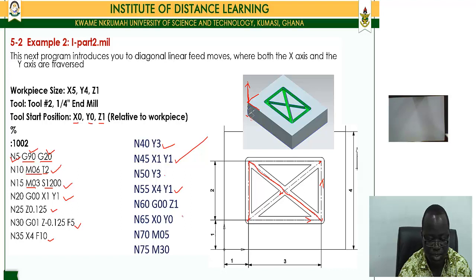And then it moves X4 Y1 here, and then it rapids to this position, and then it rapids out, and then we are through with the work.